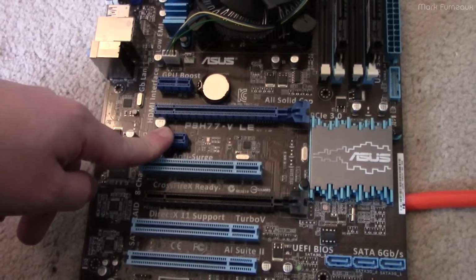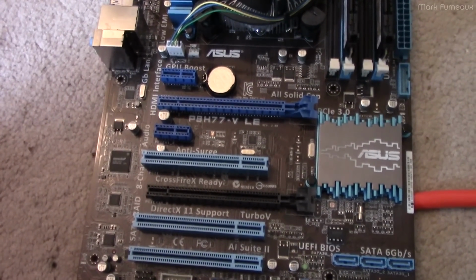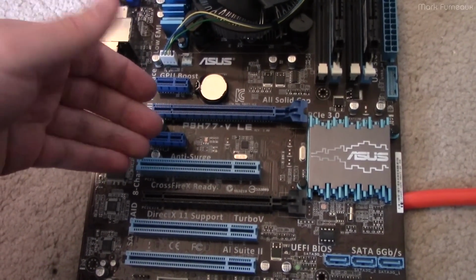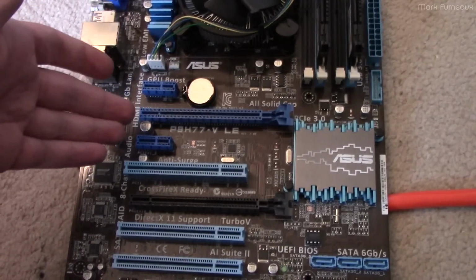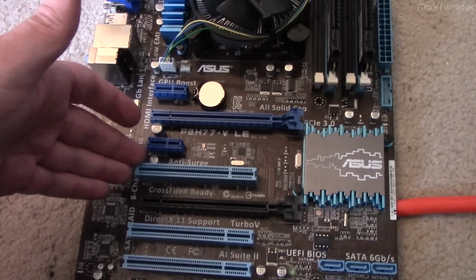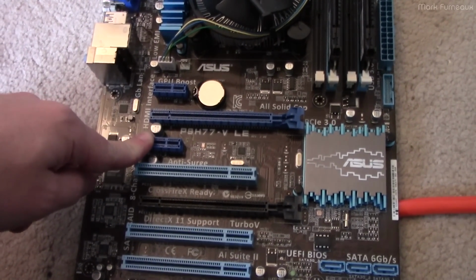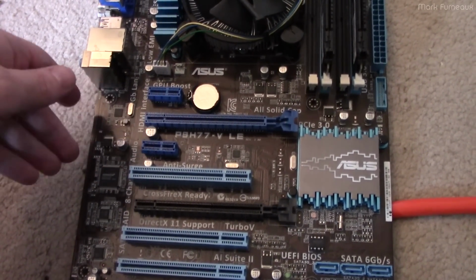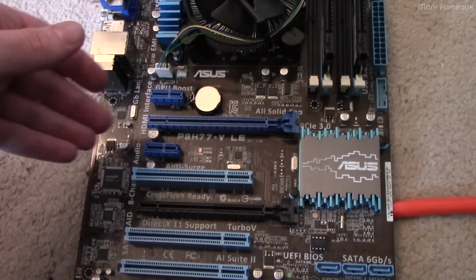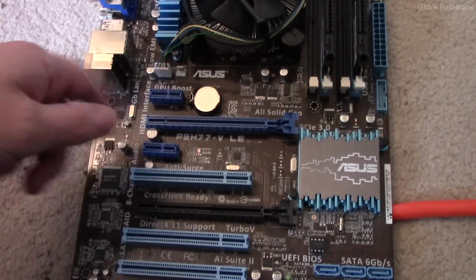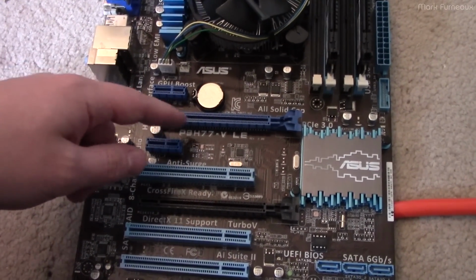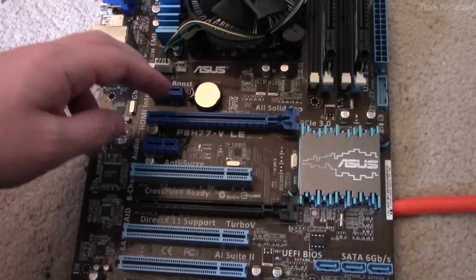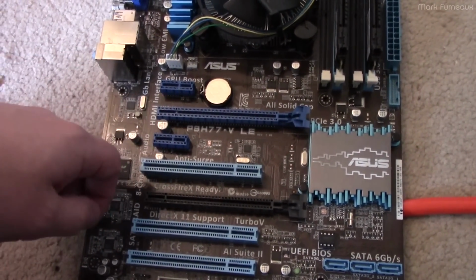It's actually common, especially on low volume or more industrial products, to buy even brand new things like CAN bus cards or serial port cards that are PCI Express cards, but the actual chip that does whatever communication standard you want is really low speed. It's an old chip and it's a PCI bus chip. And rather than designing a whole new ASIC, which is very expensive, they just put down a bridge chip, and that's what makes it a PCI Express card. So it's actually a PCI device on a PCI Express card.